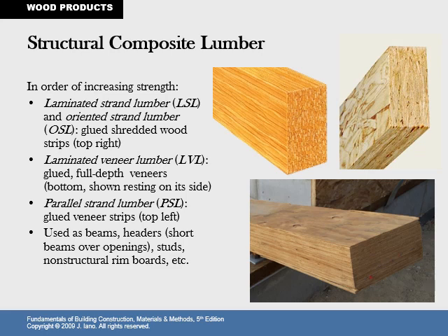Laminated veneer lumber, LVL, is glued full depth veneers, and it's shown resting on its side. So it looks a little bit more typical of the wood features that we might see on the surface, but the interior here also kind of resembles our LSL. Parallel strand lumber, the PSL, are glued veneer strips used in beams, headers, short beams over openings, studs, non-structural rim boards, etc.